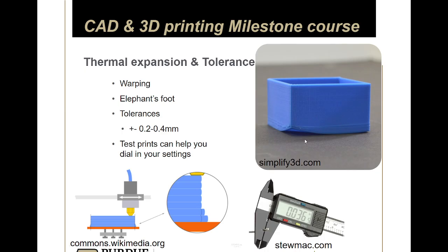One of the big things that contributes to warping is having a super long part, right? If your part is super long and all the plastic molecules start shrinking and pulling, the longer the model is, the more force it can generate to curl. So you'll sometimes see on really large models that there might be some slight bowing if their printer wasn't dialed in.